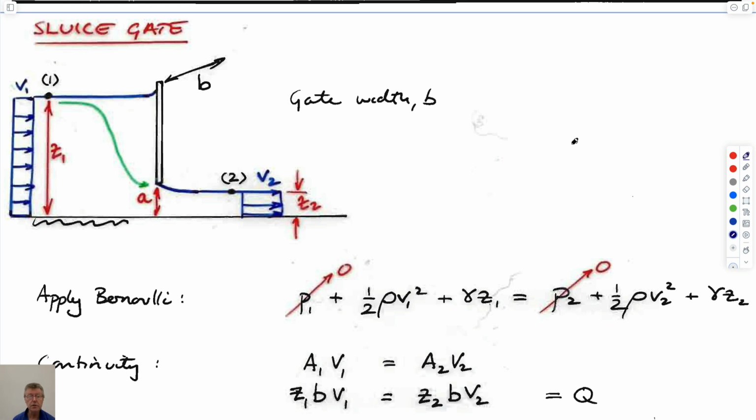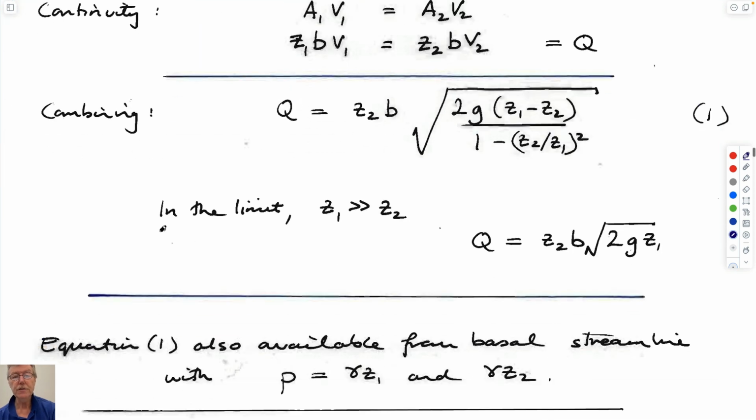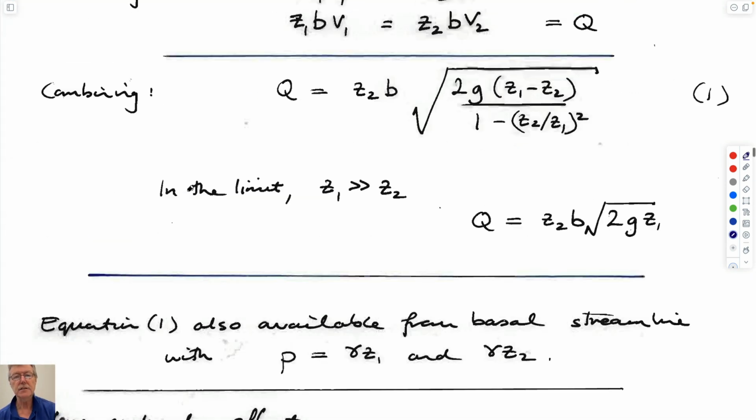So in pipes we talked about, and we've just done that example. Open channels is much the same. We use weirs or sluices. We can define them as undershots or overshots. The one we looked at in the video was an overshot. It's not unusual for you to go out as a beginning engineer and working in the field, get the flow in this ditch. You take a spade, a shovel, you put a plank across the ditch, and you measure how high the fluid flows across the plank. That's essentially what we're doing here for an overshot weir like this, which we'll get to in a sec.